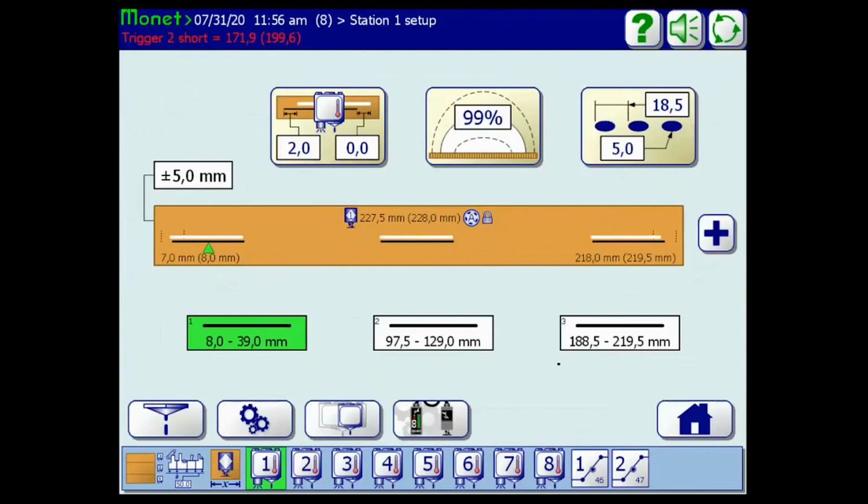hot melt detection applications. Some of that depends a bit on light spot sizes for the detection light spot sensors. But we would expect to be able to comfortably hold 3 millimeter start and end tolerances within your application. Okay. Now, if we fall out of that 3 millimeter tolerance and we start rejecting product, the question then becomes, is that product actually bad, or is it non-sellable product at that point? Right.